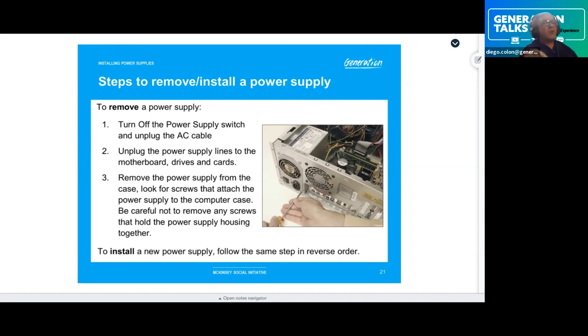The same thing, if the motherboard only has 3 prongs coming up for the CPU fan, that extra one means that the BIOS isn't a fancy BIOS, that's all it's telling you. It cannot regulate the speed of the fan. The fan will turn on and spin at a constant rate, versus all these gaming performance ones, as we saw when I went into my Alienware and turned on the power.